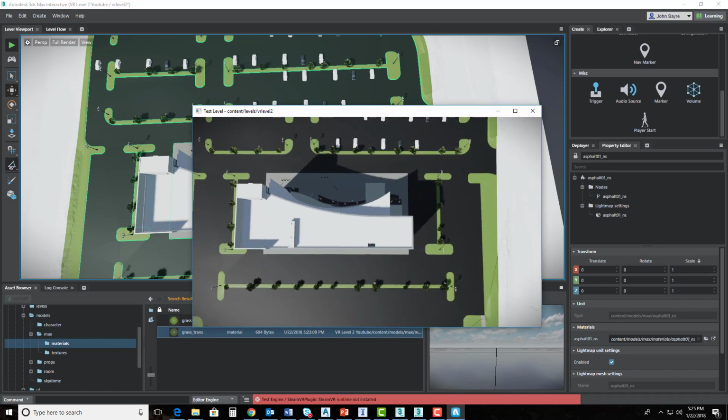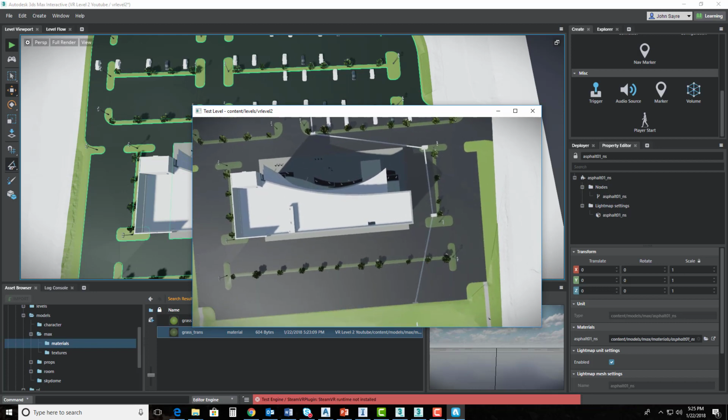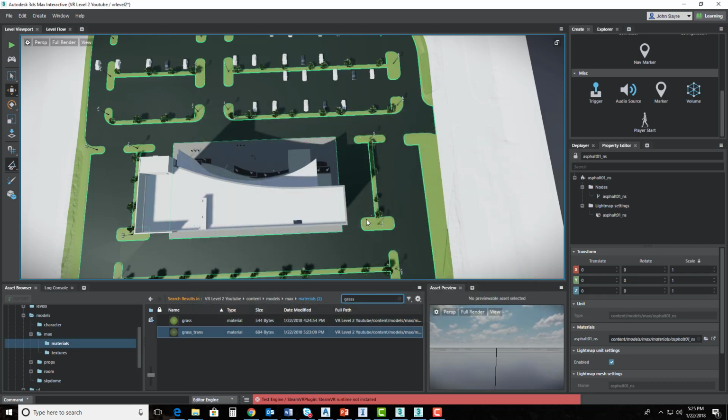And we can hit T and you can see those inlets very well. Now notice that the bottom at the outlet pipe, it's still underneath that other area of grass. So we would have to create the same flow node for that. Now, this could be taken care of by exporting out the coverages differently in InfraWorks, and I just didn't go back and change that. So it just created a little bit of extra work for me here in Level Flow,